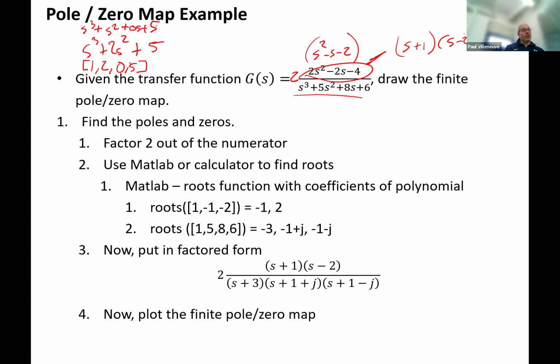Right? So you can't just throw that zero coefficient away, because MATLAB will just say, oh, if you just gave me 1, 2, and 5, that means it's s squared plus 2s plus 5. But in actuality, you have an s cubed. So I think that also applies, well, maybe not in C-solve. Didn't C-solve on your TI, do you actually enter in the whole expression with s terms and everything? It probably has a similar feature where you can do roots, I don't know, but I just find it easier to do in MATLAB.